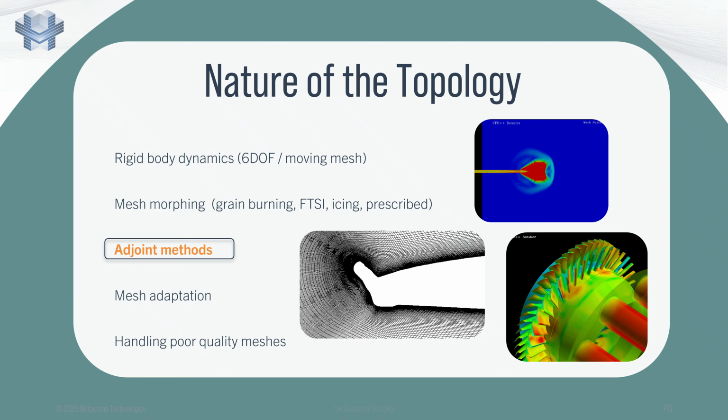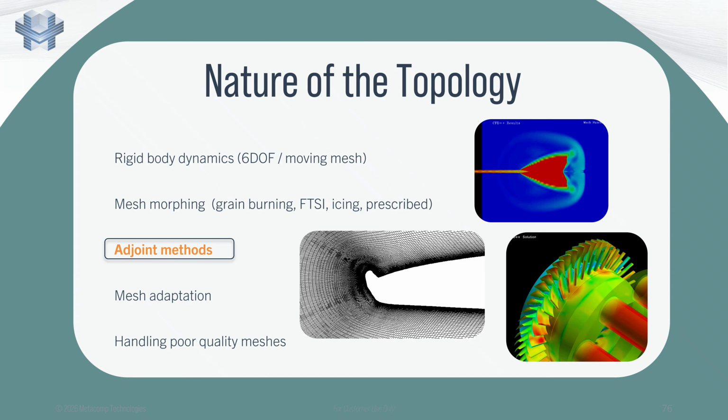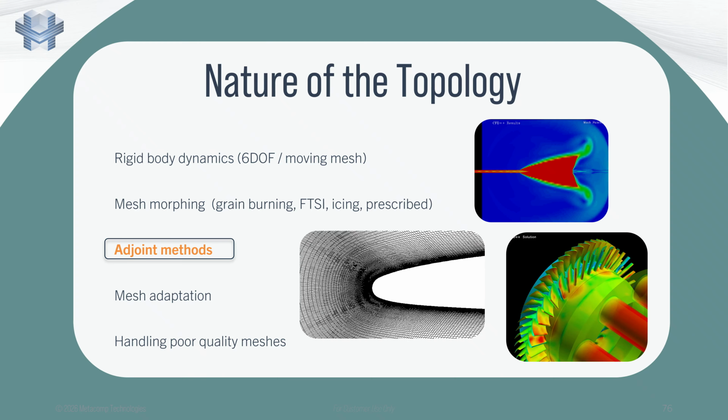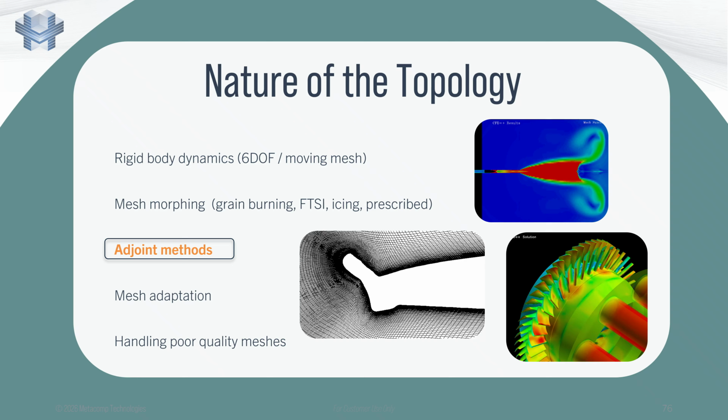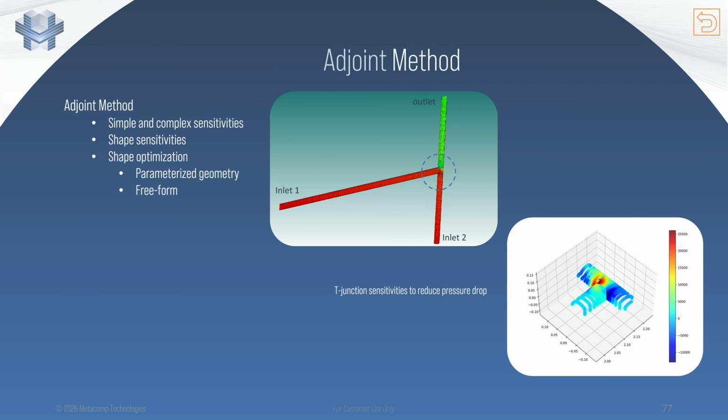The Adjoint method provides a powerful and efficient way to compute gradients in optimization problems, enabling the development of complex models and improved designs. The Adjoint module in CFD++ enables users to efficiently assess how changes in input parameters impact a wide range of outputs or objectives, rather than requiring a full recalculation of the flow solution for each input modification. A single Adjoint solution suffices for each objective. This approach is especially effective when analyzing the influence of multiple parameters on a single objective, significantly reducing computational effort.